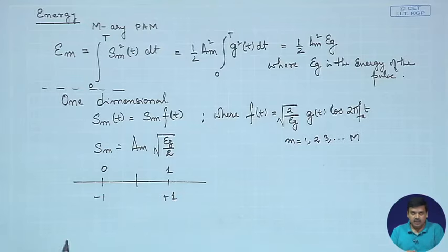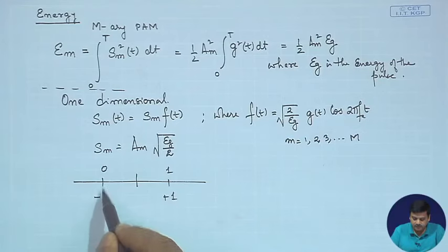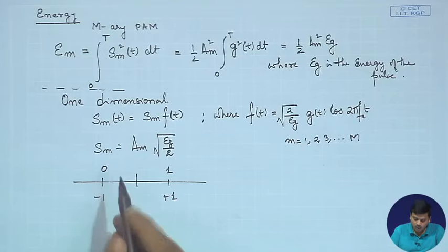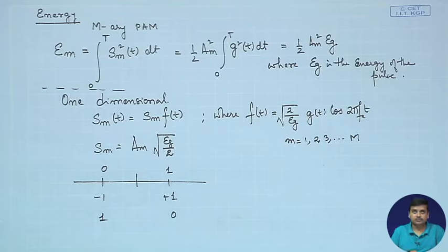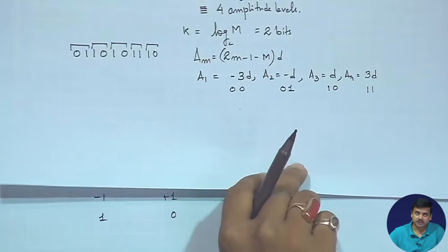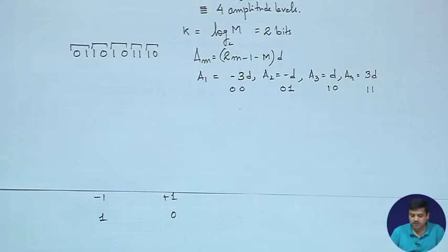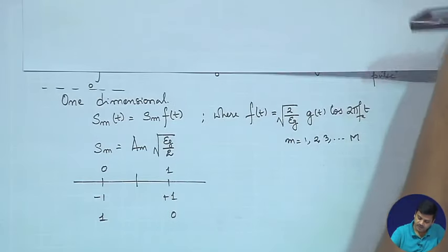Now, at this point, it is crucial that we look at what kind of mapping that we do, because we are discussing the symbol mapper. We have already talked about two different kinds of symbol mapper, that means one which selects between two amplitudes and the one where there are 4 amplitude levels. So, in the 2 amplitude level case, your life is simple. So, you could select the negative with 0, or you could also use this notation, and then things will be quite manageable, there will not be any differences. But if we look at the 4 level mapping, that means if we take the example that is here, then the situation is pretty different, because you have several combinations.